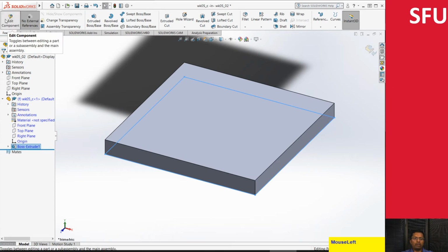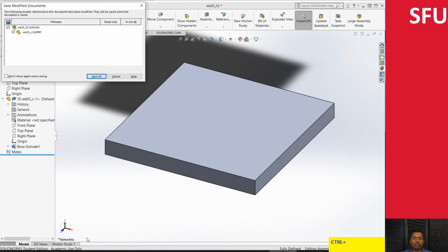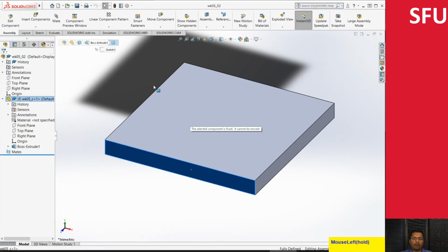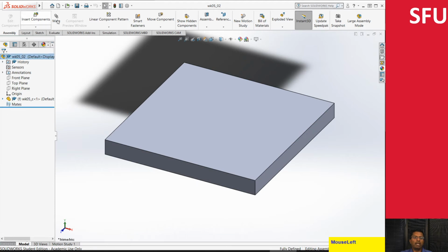And we are basically going to click on this edit part again, which closes the part and goes back to the assembly. So now I say save all. Keep in mind that this is the first part I imported, so I can't actually move this part anywhere. It's kind of fixed in place. And again, this has an F, which basically indicates it's fixed.